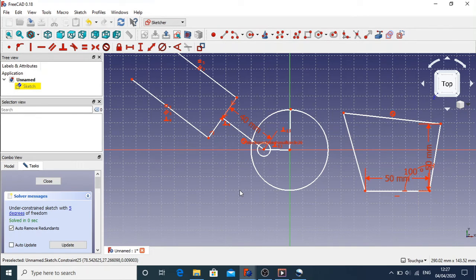As well as block constraints, you've got lock constraints as well. So this one here. What a lock constraint will do is lock the geometry in reference to the center of origin. So these lines here, these are your axis lines. So now there we go, there's the sketch axis lines. For me to lock this geometry, let's take off this block constraint for a minute.